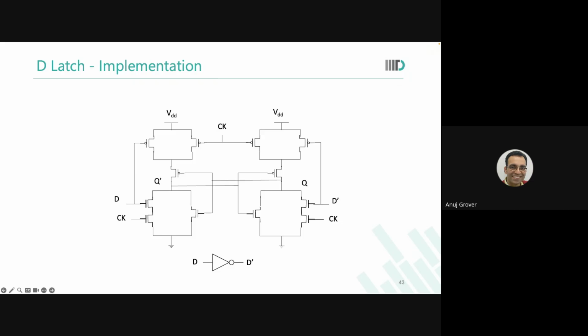We did that. All of this jugglery we did in DVD also. Did we not? We said let us make pseudo NMOS, let us make dynamic, we do this, we do that. Whenever we deviated from CMOS, what happened? We saw that there are some new constraints which will come. Do you realize that? We said pseudo NMOS, we said sizing ratio, we said dynamic, we said charge sharing. So somewhere we put a keeper, somewhere something else. We had to do something to handle it because static CMOS is the most robust. You are deviating from it, something will come.